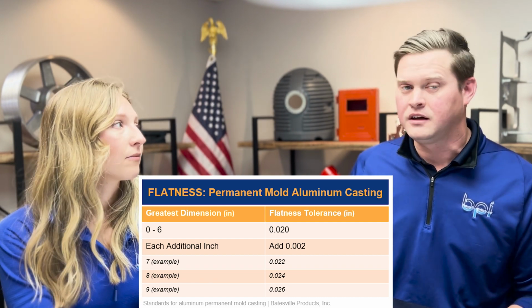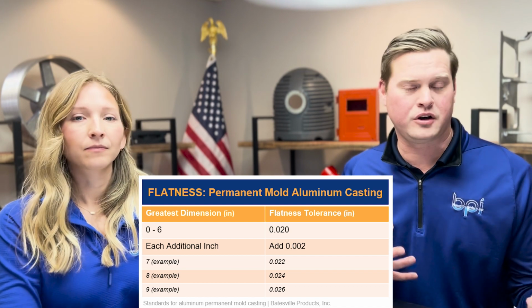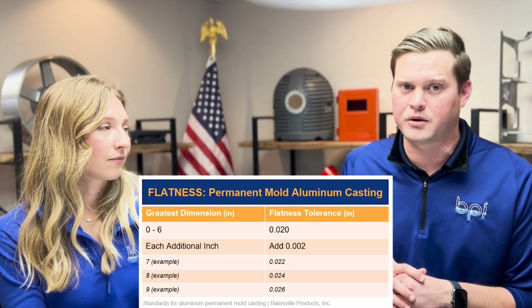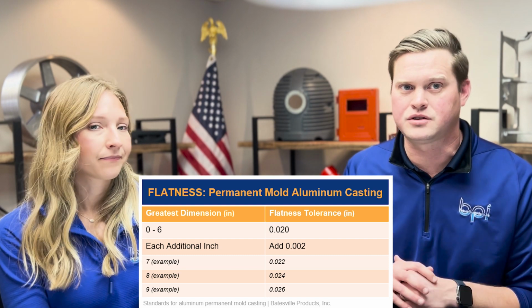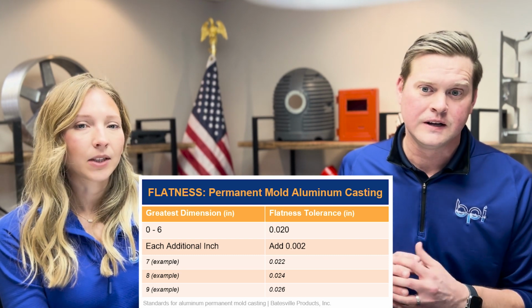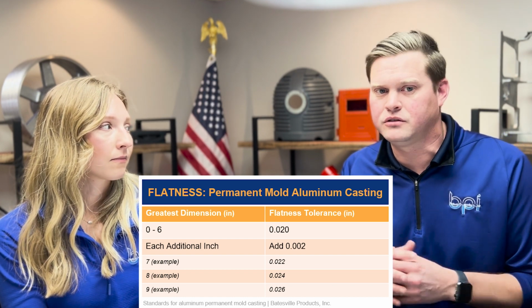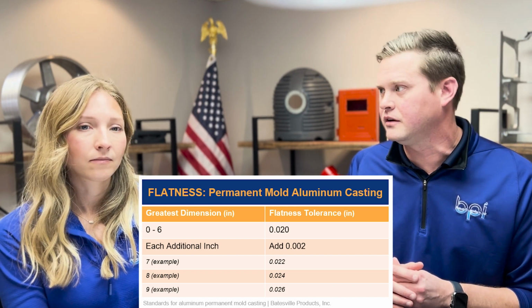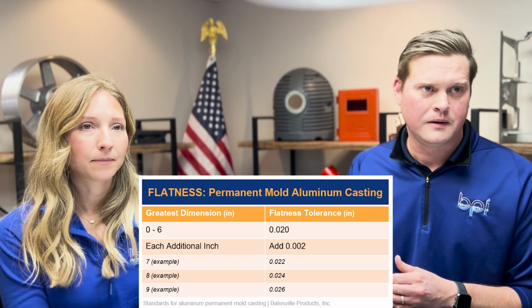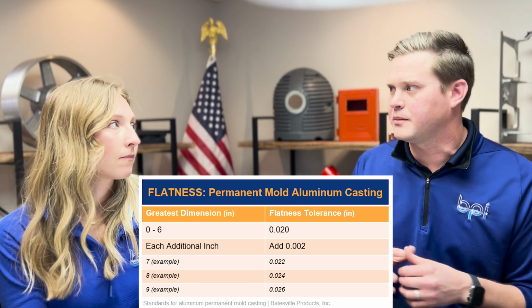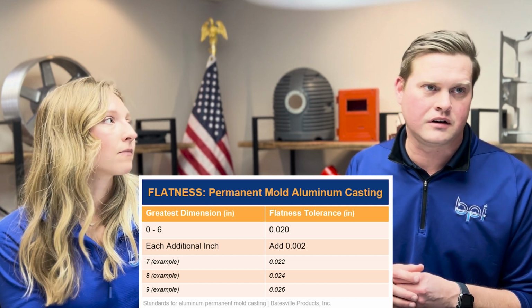Yeah, it does add strength to the part. You're baking it, but it could add that potato chip effect, or it could bend the part based on the heat treat, based on the quench following it. Yeah. So when you're designing, it's something to keep in mind that we don't really go into too much detail on here, but something to think about. Yeah. And oftentimes it allows us to add that extra step of flatness and straightening the part as well.